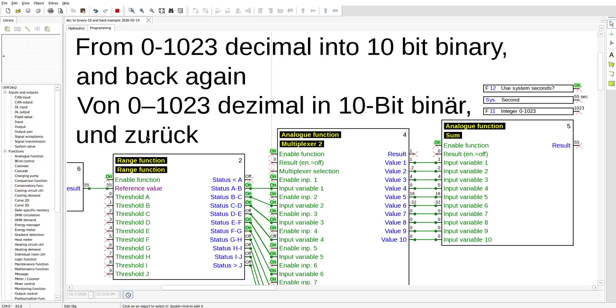In this video, I would like to show how you can use an analog value, as they call it in Technische Alternative, in this TAPPS2 program, to hold up to 10 digital values. Now, analog is actually digital, and these values here are binary. Anyway, you sometimes run out of inputs, outputs on the CAN bus, or if you even want to link it to Home Assistant or something.